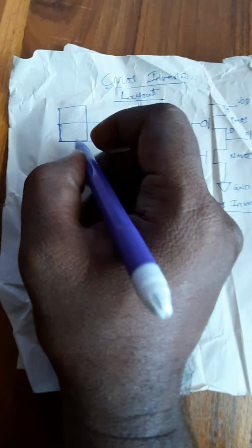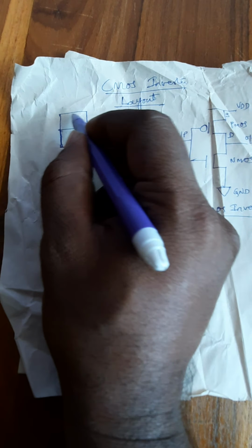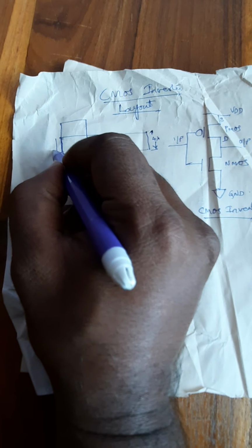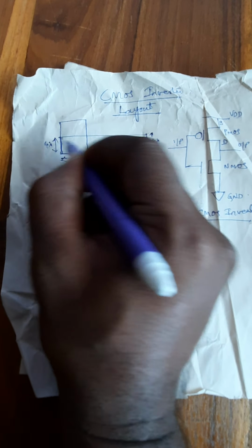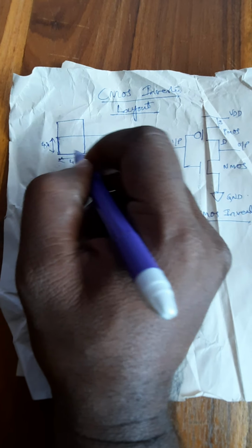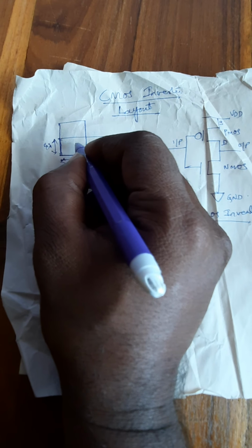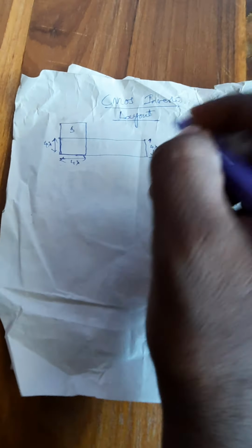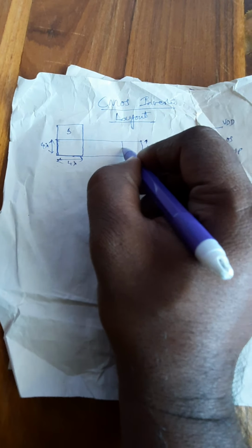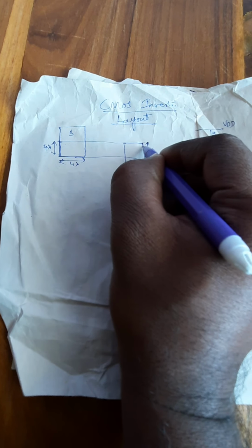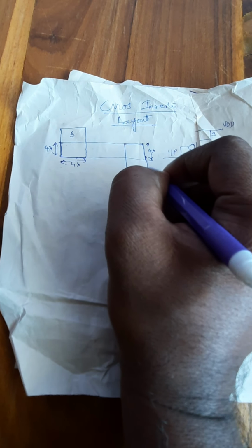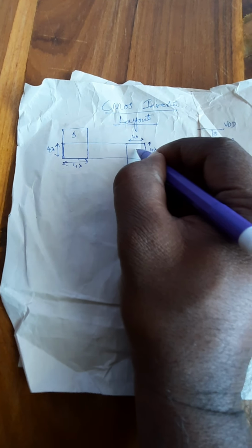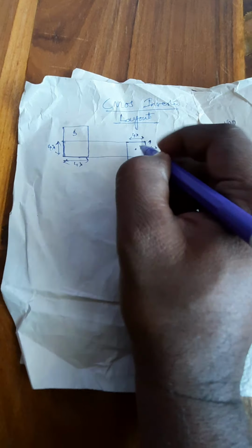with a layer called the metal layer. I'll use a metal layer in the 4 cross 4 dimensions. This is the width and the length of the metal layer, 4 cross 4, and this acts as my metal layer, which will be called the source terminal. This is my source terminal, and then similarly over here I'll draw a 4 cross 4, width 4 and length 4, for the drain terminal, and this will act as the drain terminal.